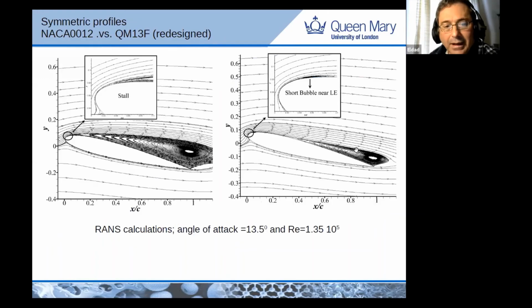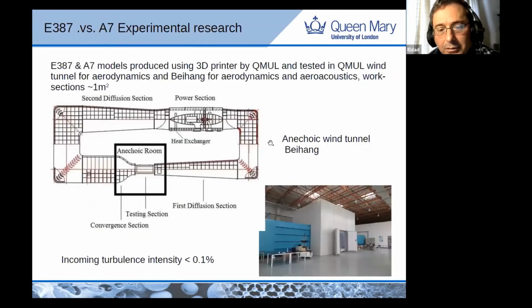Okay, so this is the aerodynamics, and we can see over here the effect. This is actually for NACA 0012. Same exercise done. The bubble still exists. This is aerodynamics. Then we go to the question: that affects stall, but will it also affect noise generation? Obviously, we will not get stall noise because we're delaying stall. But what happens at low angle of attack?